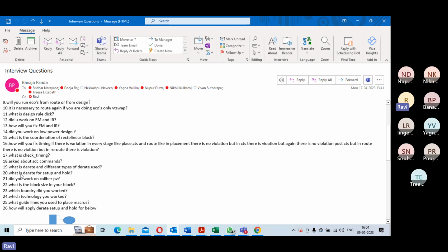And again, if you look at TSMC documentation, based on your IR drop, it will give a certain derate, and based on your temperature variation, your junction temperature, again there's a derate, because as your junction temperature increases, the variation will increase. So there is a temperature dependent variation and an IR drop dependent variation, which you'll have to use for your various factors. So junction temperature and this one you will have to apply.